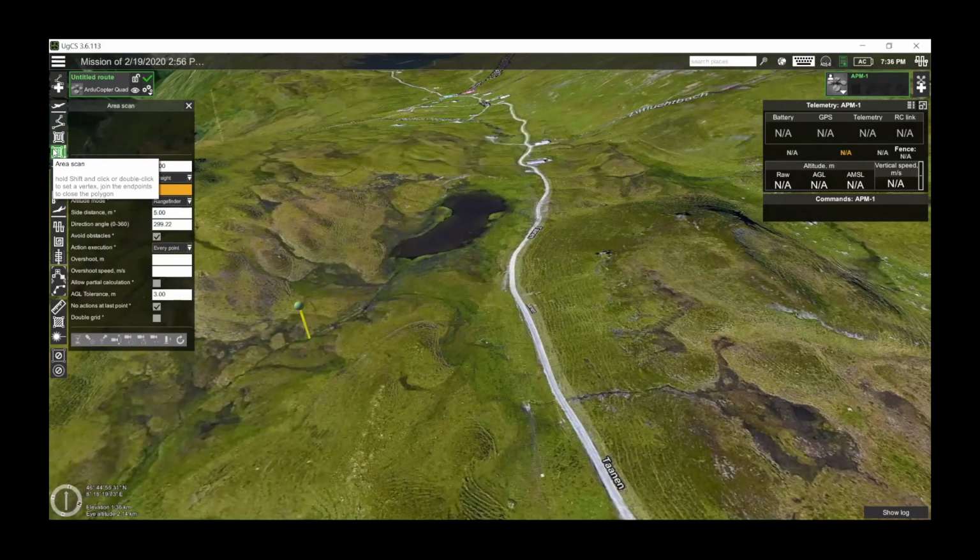This can be used for all types of flights. It is very recommended and very useful for flights at lower altitudes because of GPS floating and barometers' possible floating. So on long flights at, for example, 5 or 10 meters above the ground level, the altitude may start floating, and there are some safety risks. With a laser altimeter, the drone will have the real altitude towards the ground all the time.